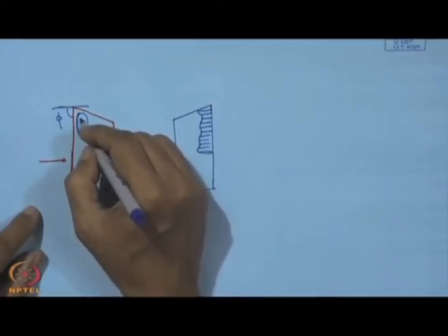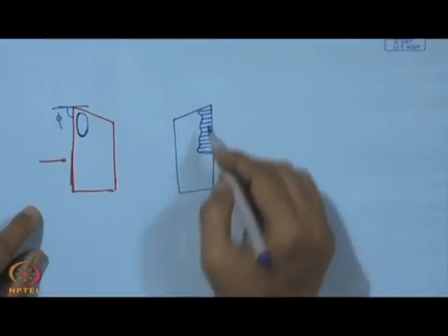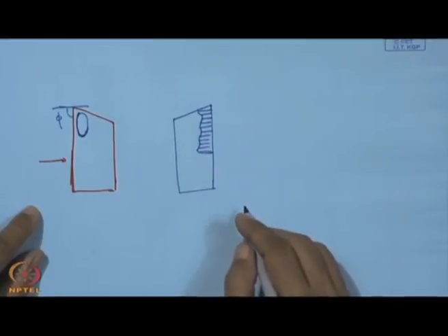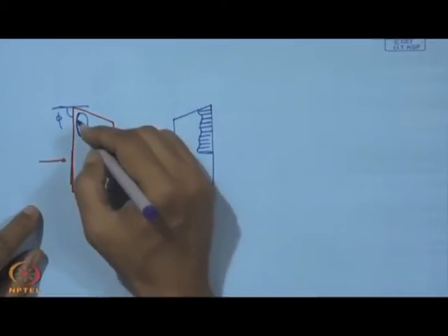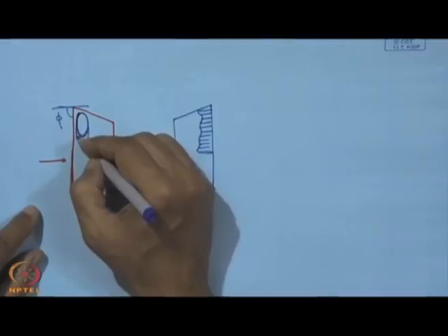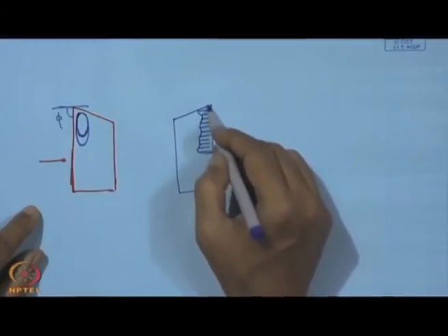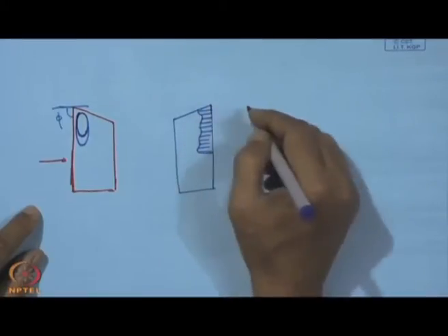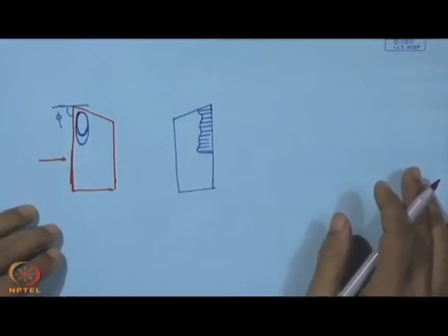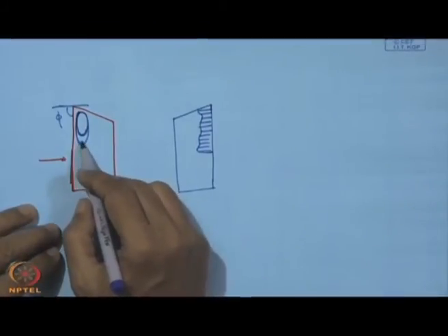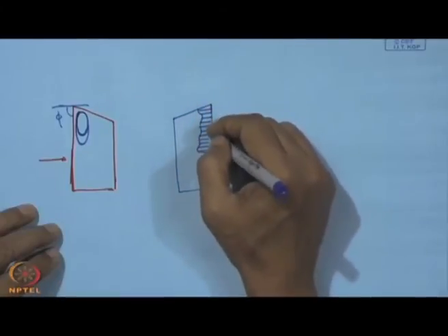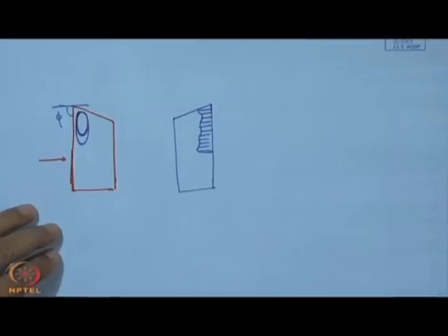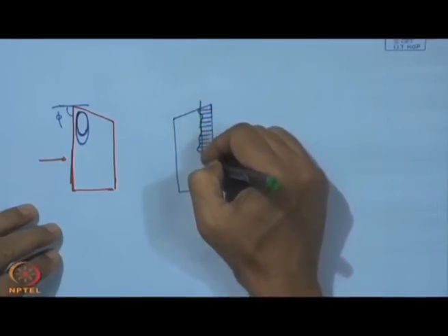With this cratering, cavity formation and this wear land formation on the flank, the tool will lose its cutting capability. This width will be almost equal to the width of the chip, because the contact zone is equal to the width of the chip. So, here we get such a thing, and this has an average value. Say we can show this average value by this line.